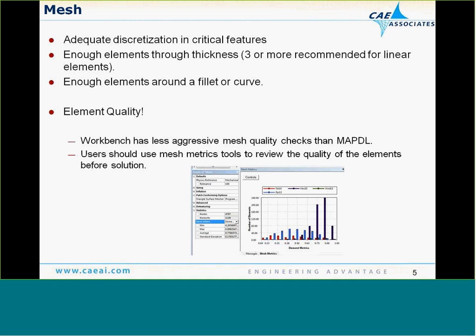When you use Workbench, it generates a mesh. It has less aggressive mesh quality checks than MAPDL has, for those of you who used to use classic ANSYS. But Workbench offers a mesh metrics tool that will let you review all of the quality measures before doing a solution.